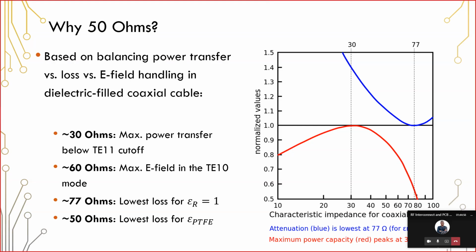So generally, if you're working with RF signals or an RF system, and you see any kind of signal integrity guidelines, or any kind of component specifications, if they're operating on a PCB, they're generally going to be specified at exactly 50 ohms. So there will be a requirement in the design to design transmission lines to 50 ohm impedance, unless the component data sheet or some other system specification dictates otherwise.